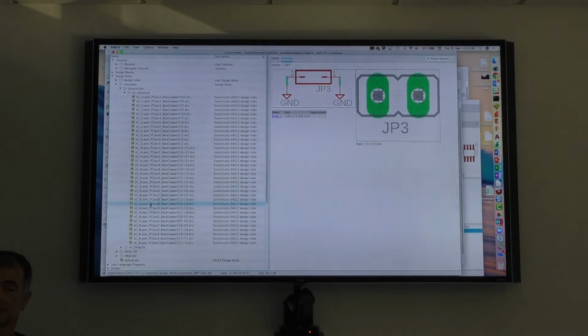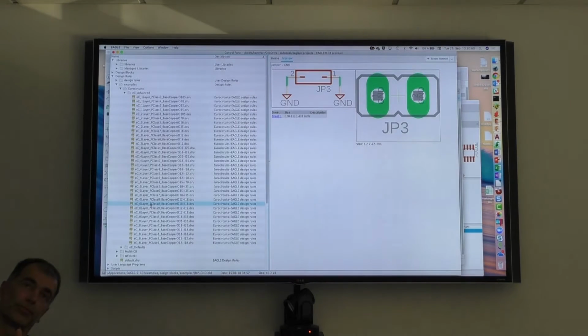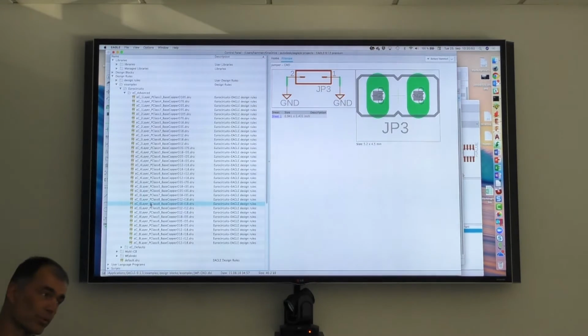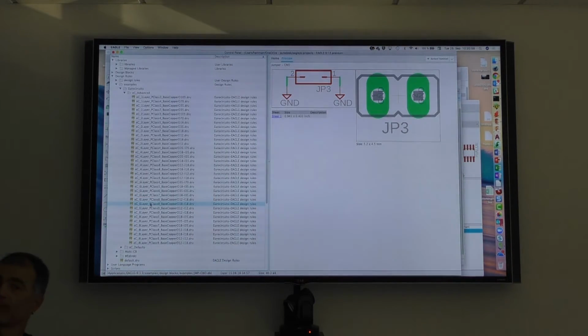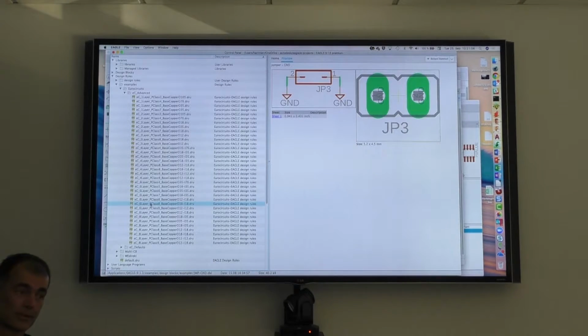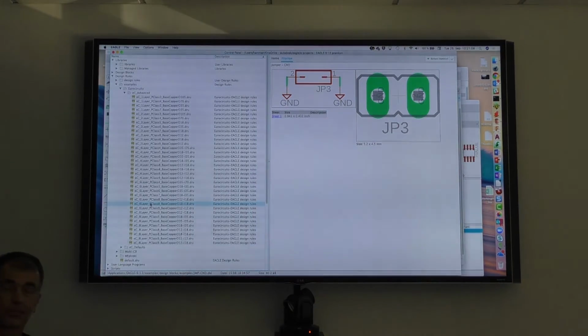The default structure is 150 micrometers copper and distance between copper. So that's what you can have. It goes down if you have 125 micrometers. That's a bit more expensive. 100 micrometers. Eurocircuit, I think, offers 90 micrometers in width and distance or clearance. And there are even manufacturers that can do it smaller, 15 micrometers.